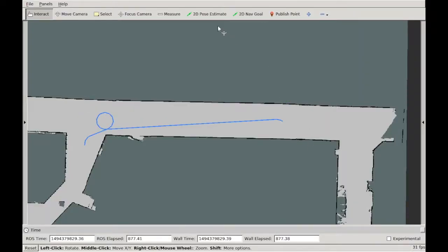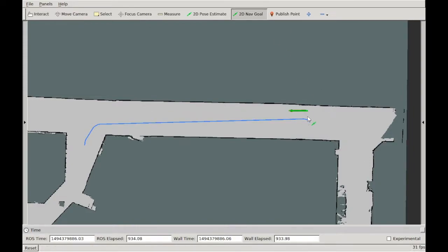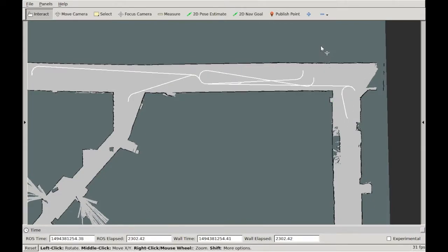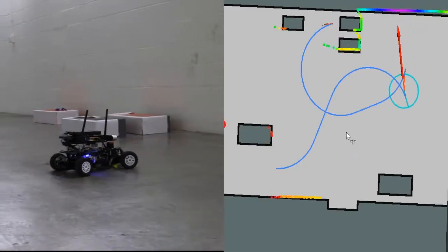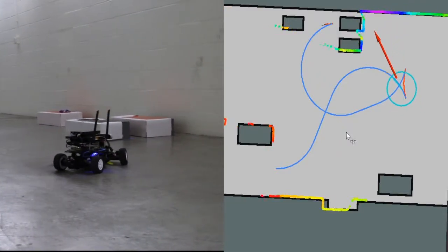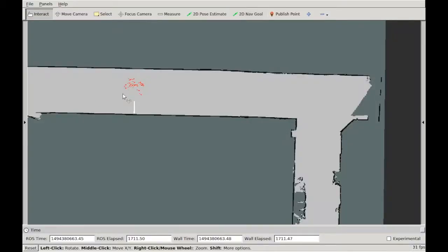It can generate paths that go forwards, or ones that go forwards and backwards. These are the trees generated by RRT. Our trajectory tracker can drive paths that reverse directions and self-intersect. In order to swerve around cones, we create fake walls, shown in white, and then plan around them using RRT.